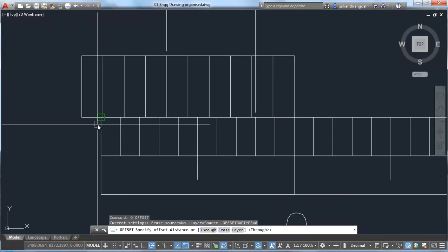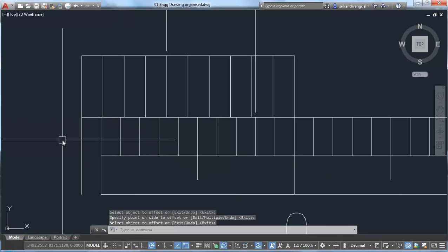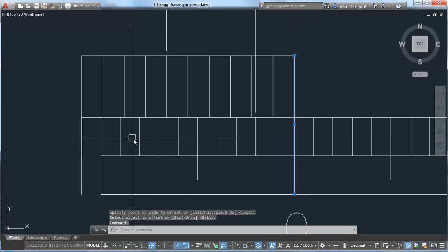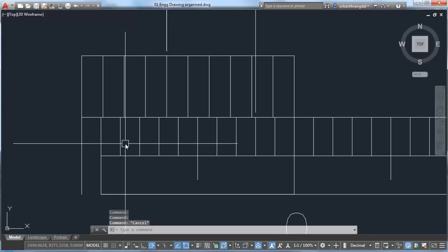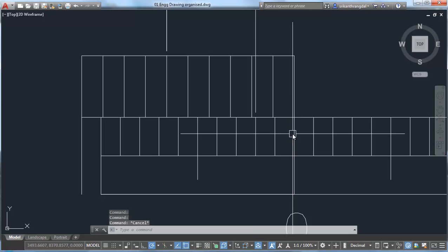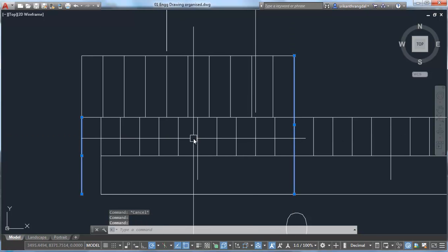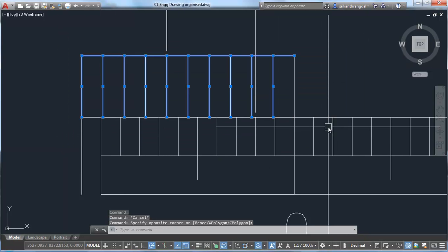So what happens with the Vernier scale is I take this same distance, 1 extra. As I told you, the distance between these two lines is exactly 1 meter, and the distance between these two lines is 0.1 meters. So when I take this length exactly extra on the other side, the total distance between these two becomes 1.1 meters. And that 1.1 meters we are subdividing into 10 equal parts.